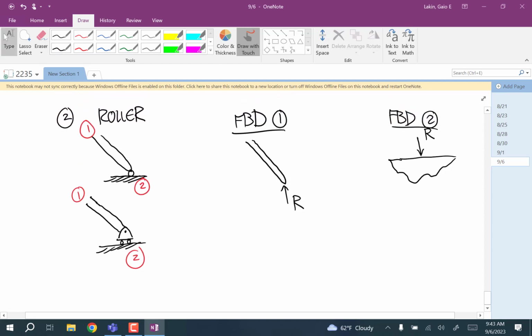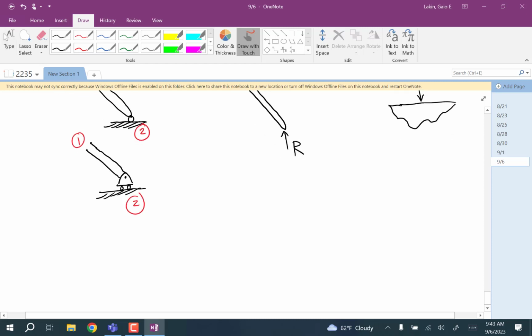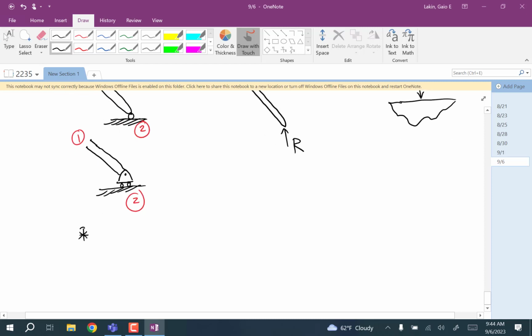What about this one? Could that R be negative on a roller? No, because if you got a negative answer for that, again, that would be like the ground pulling down on the wheel on the roller. That doesn't happen. So again, R has to be positive.